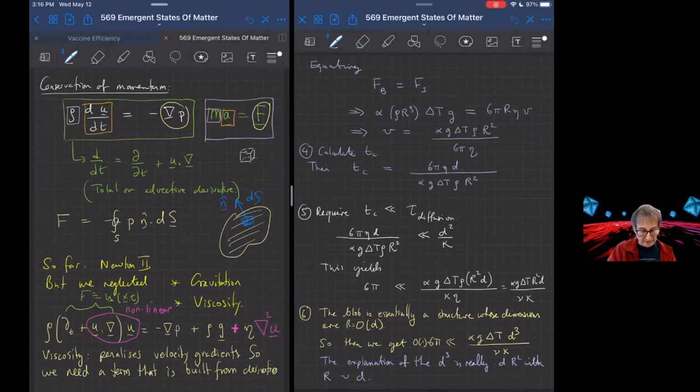The terms you can see here represent, on the left, the nonlinearity due to advection. That's the u dot grad u term, the term that makes fluid mechanics so complicated. Then the gradient of pressure, which is just the force applied to the system. The density times the gravitational field, that's rho g, the potential energy from the gravitational field.